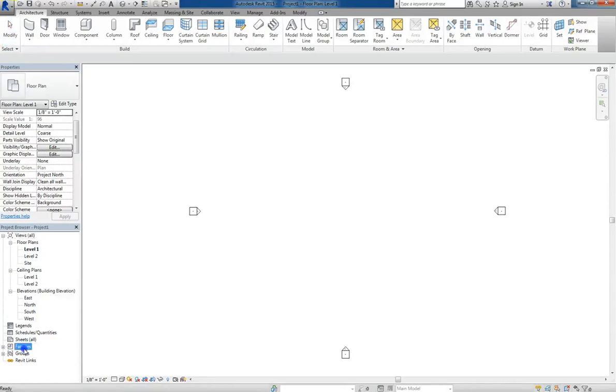Families, which are something we're going to get into later on, are all of the components that are already built into your file, even if you haven't started using them yet. There's different doors, ceilings. This makes Revit files tend to get pretty large. You might have seen some files in kilobytes or megabytes. Revit files can run from 2 up to 500 megabytes. So these files can get pretty big, but the reason for that is because they contain so much information.